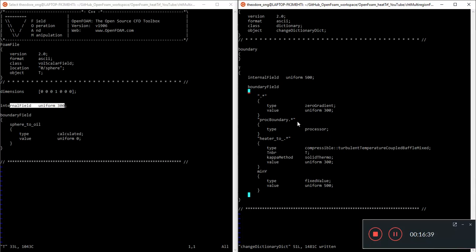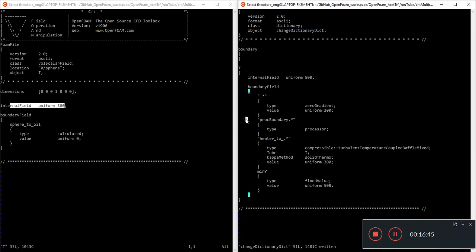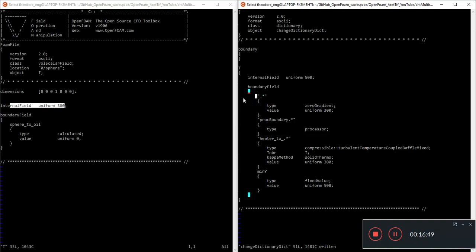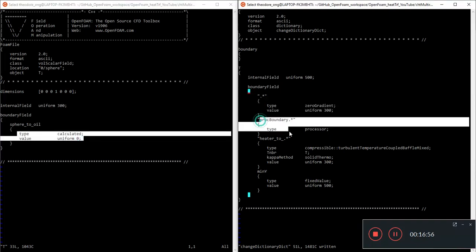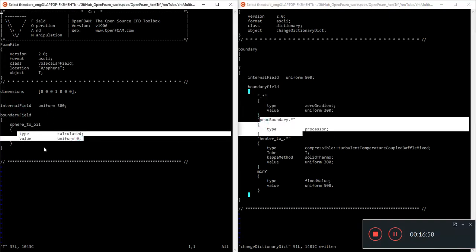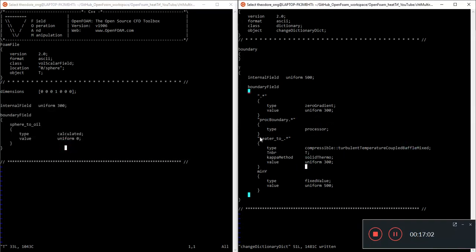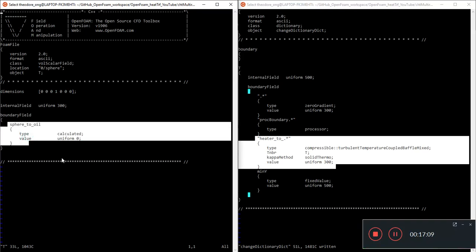But OpenFOAM is just going to read this one first. It's going to read this entry. Then anything over here is going to replace the entry. So OpenFOAM is going to take this zero gradient uniform 300 and replace it here. Then it will say processor boundary. Okay, is there any processor boundary here? If not, then we'll just leave it. Next thing it's going to look for is heater 2 ... and then it's going to search this one for heater 2 ...